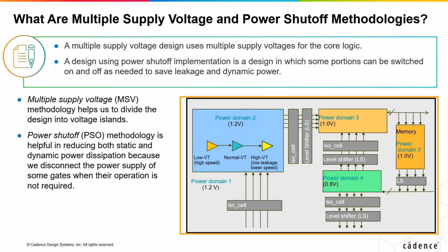As you can see in this block diagram, the various voltage islands have been made, and the corresponding power domain is assigned to them. Out of these, some of the power domains contain the PSO implementation, and hence they can be switched off when required.